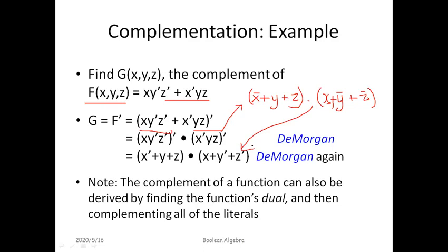This is by use of what we call De Morgan's laws. Let's make sure that we understand and master De Morgan's laws. They'll be very useful in your mock examination, even the final examination. So note that the complement of a function can also be derived by finding the function's dual and then complementing all the variables or literals.